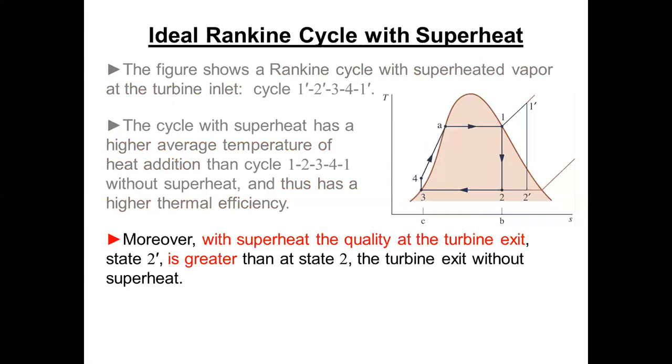And then now he's making the point about how the steam quality is larger over here at 2' than 2, and so the turbine would really like this. And, okay, so we're going to slide the quality box over from 2 to 2'.